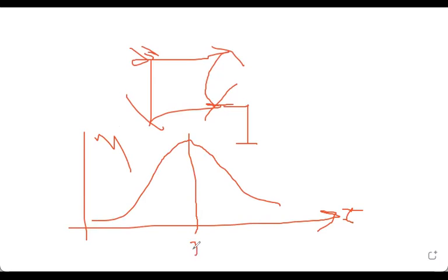This is around 2.7 sun, which is typically 2700 watt per meter square. What happens? The higher the intensity, the higher the efficiency. So whenever you increase your intensity greater than 1000 watt per meter square, you should typically expect higher and higher efficiency.